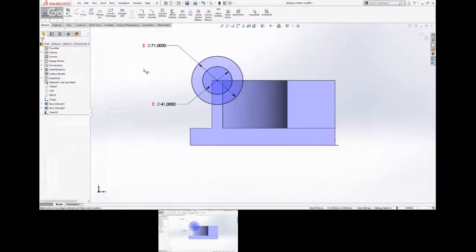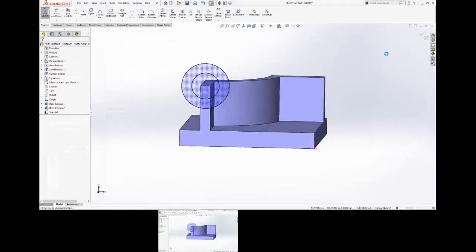Okay, and if you're quick on the double enter or tapping enter twice, it'll accept it and close the dimension tool. I do notice that I have to move my mouse off the dialog. Otherwise, it just seems to get tied up there for some reason. So there's our sketch there. And then we're going to do an extrude. So we'll grab the extrude tool.